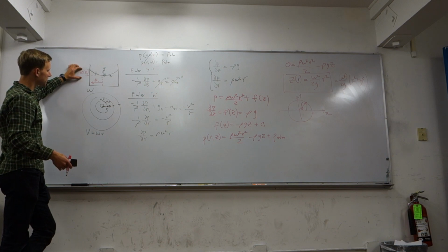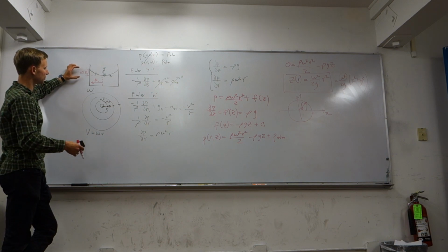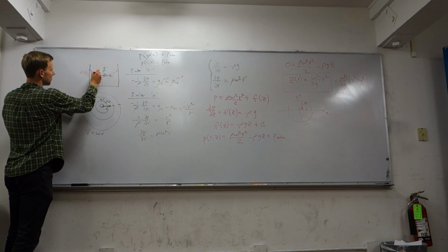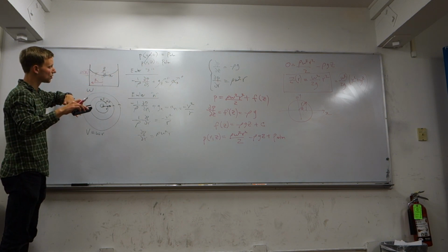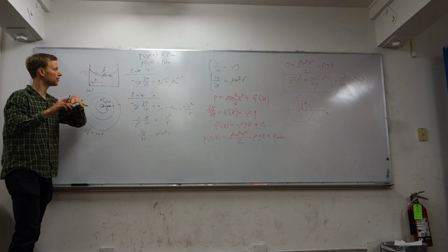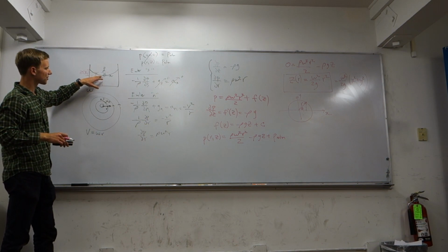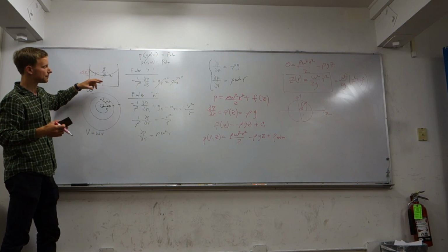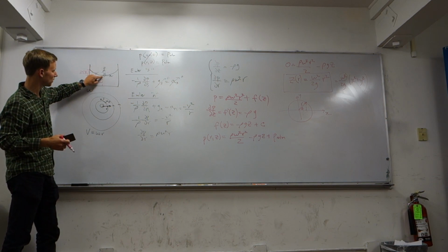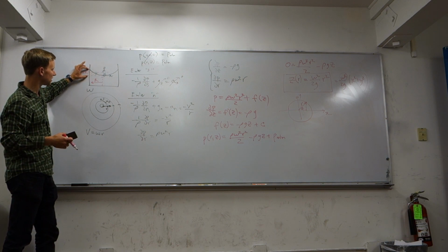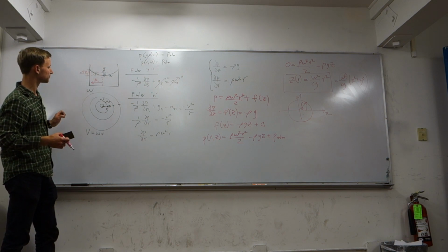So to perform this experiment, it's not sufficient to simply measure the initial height of our fluid and then measure the new height, because you'll notice that the center drops because mass balance says that it has to. So we'll need to come up with an experiment so that we get the vertical distance between the origin and the edge of the free surface here.